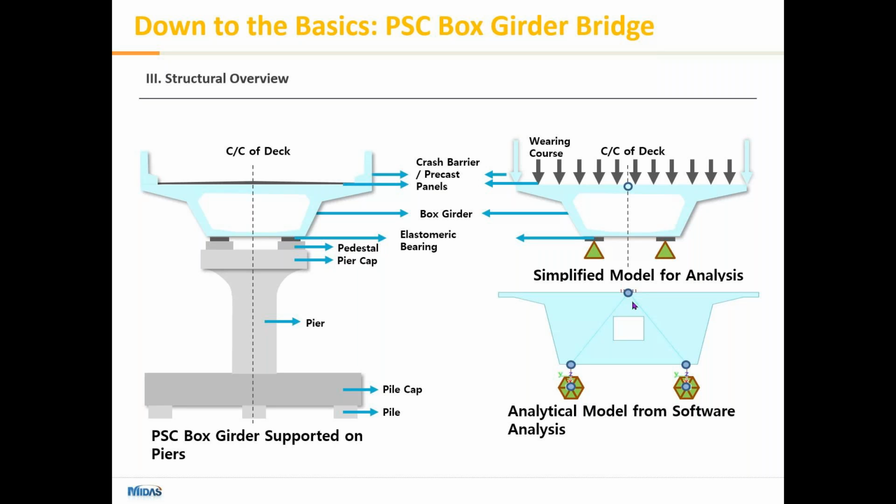On the same lines, in center top modeling, the section will be shifted in such a way that the modeling will now be done on the basis of the center and the top of that particular section. What I mean is, for this particular section, we know that the CG will be lying somewhere here, right? But now I am considering the center top approach. So now my whole section will be modeled from this particular point. This will be my center top point.